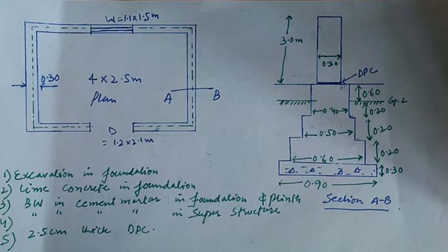In case of a building having different types of walls, suppose the outer walls are of the A type and the inner walls are of the B type, then all the A type walls shall be taken jointly first, and then all the B type walls shall be taken together separately. In such a case, no deductions of any kind need to be made for the A type walls, but when B type walls are taken, for each junction a deduction of half the breadth of the A type wall, that is the main wall, shall need to be made from the total center length of the walls.